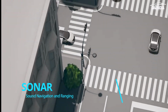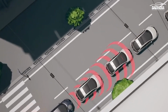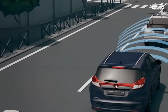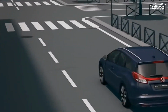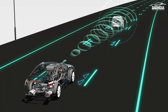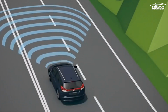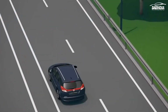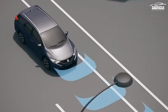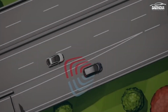Sound navigation and ranging, shortly SONAR, also known as ultrasonic sensors. SONAR sensors generate high-frequency audio of the order of 48 kHz, more than twice the human hearing range. When instructed by the car's electronic control unit, the ECU, these sensors emit an ultrasonic burst, and then they listen for the returning reflections from nearby objects. By measuring the reflections of this audio, these sensors can detect objects that are close to the vehicle. Ultrasound sensors are heavily used in backup detection and self-parking sensors in cars, trucks, and buses. They are located at the front, back, and corners of the vehicles.